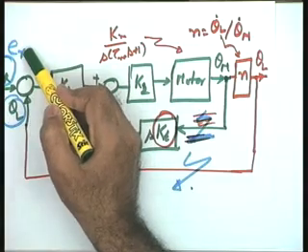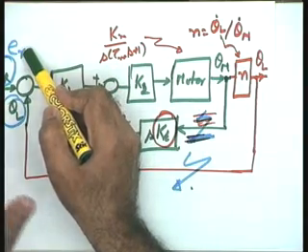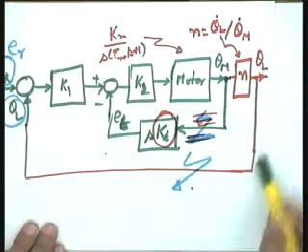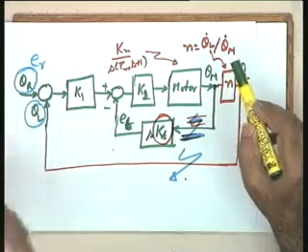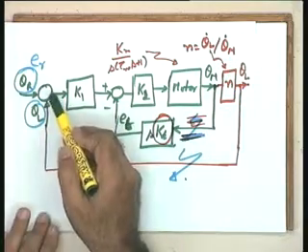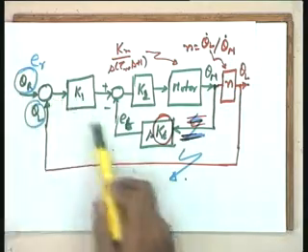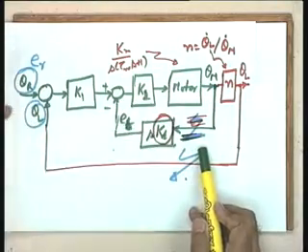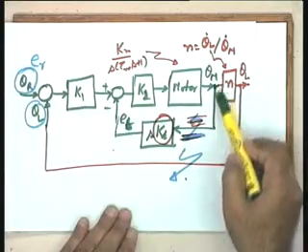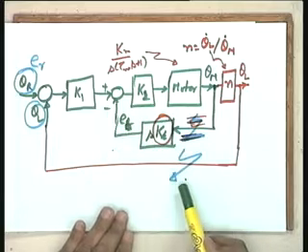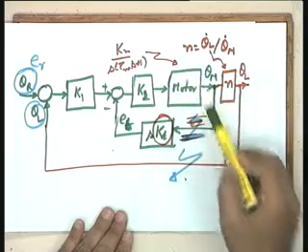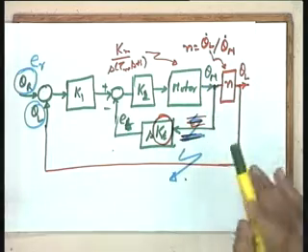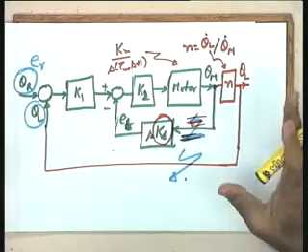This theta r is not important, you see. This is the voltage which earlier was interpreted as a signal proportional to position, because a feedback of position signal was coming. Now this particular voltage is actually representative of speed, because there is no position feedback loop. So this particular voltage ER, which is going in the forward loop, is a representative of speed now, and a speed feedback is coming in this particular case. Please see if this loop is broken. If in that particular case the primary feedback loop is that of speed, and therefore the system acts now as a speed control system. Okay?